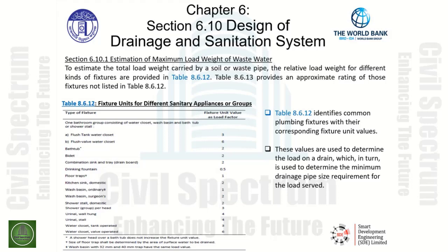We could utilize this to size the correct pipes for fixtures and multiple fixtures being connected to other parts of the piping system. We need to go to this table first to get the initial values for the fixtures as they start to discharge into the system.